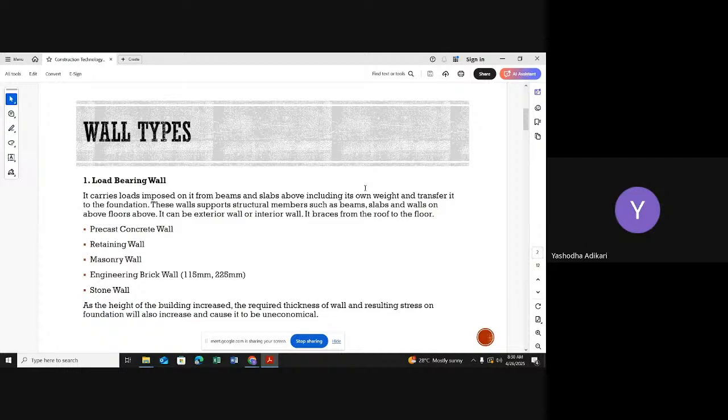First I measure the slab and calculate the concrete requirement. Imagine the concrete requirement was 30 cubic meters. I make a call to the concrete plant and inform them about my concrete requirement, the required time and the date. I tell them I need 30 cubic meters of concrete tomorrow at 5 p.m. At that time, they should transport the concrete to the site.